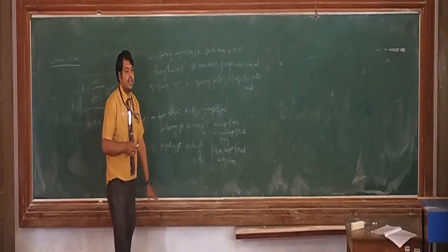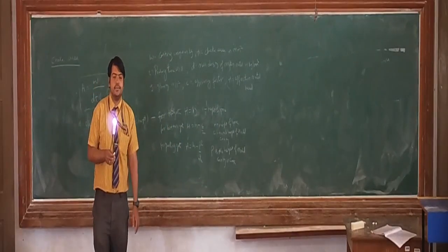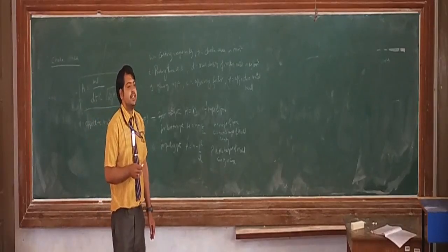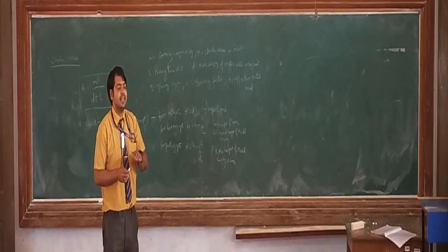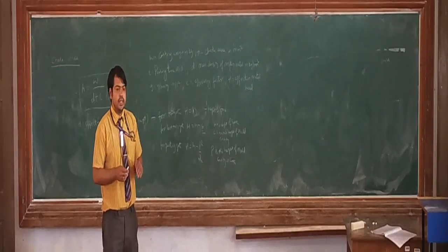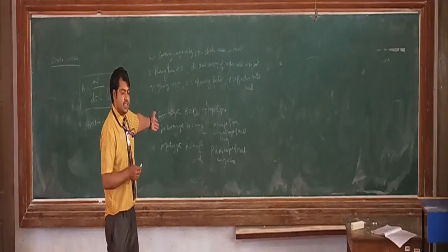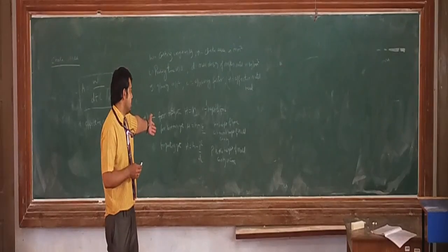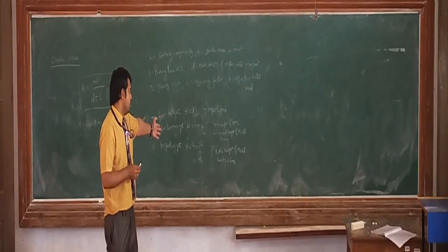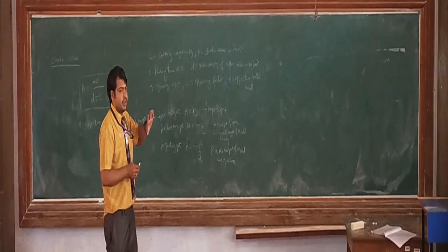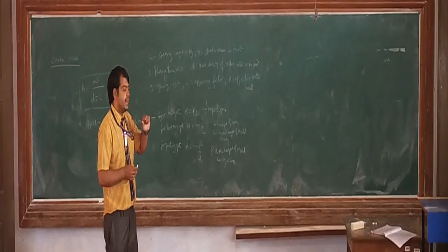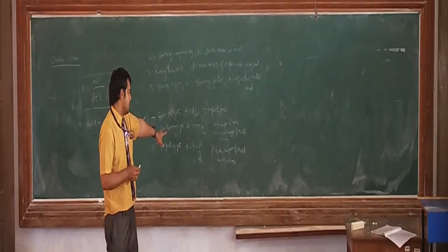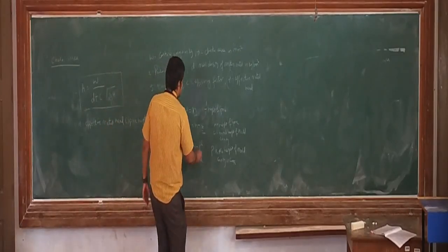Then for parting line gating system, that is the gating system where exactly the runners and the gates and in-gates are going to fall at the parting line, the separation between the cope and drag, that is what we call it as parting line. And for such type of gating system, we have this equation. So the effective metal head H is equal to H minus P square by 2C. Again, H is the height of the sprue and P is the height of the mold cavity only in cope part. Okay, because sprue base is going to come under drag part, so that is not considered over here.